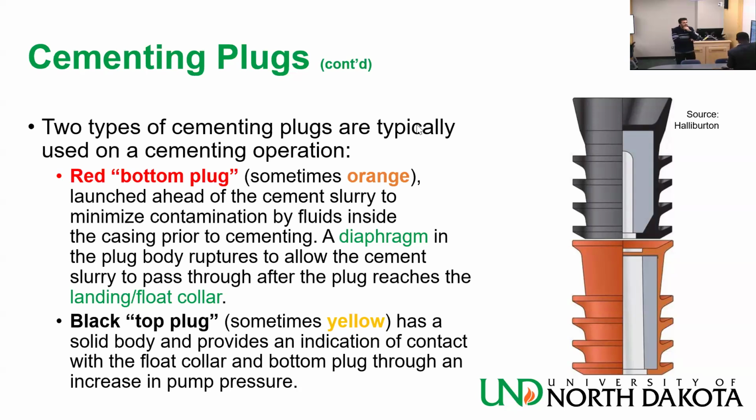and then be inside the wellbore. So the only way is like you have done a plug and abandon like that. It's basically you're going to lose the well. You rather go elsewhere and start drilling another. So you can't do anything. You can drill through, but it's not worth it. Most of the time it's not worth it. Well, it depends also how tall the column is. If it wasn't a very tall column, you might. But I mean, it's a big mistake, right?